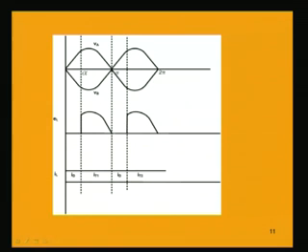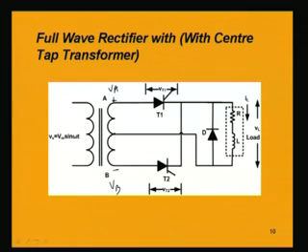Now, in the negative half cycle, when the VA enters negative half cycle, VB becomes positive, but the conduction will not take place in the lower thyristor T2 till another angle alpha beyond pi, that is, it will be conducting at pi plus alpha only. So, within this region, from pi to pi plus alpha, what will happen when VA enters negative half cycle?